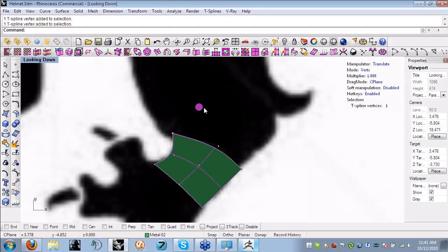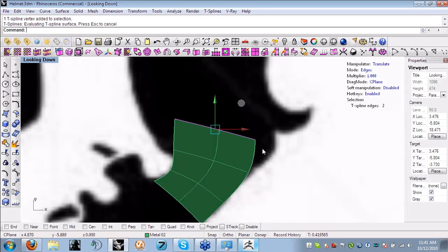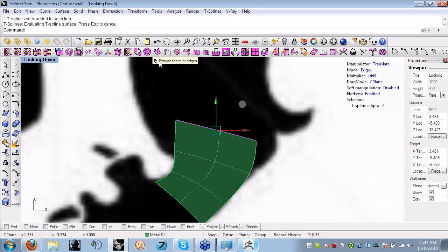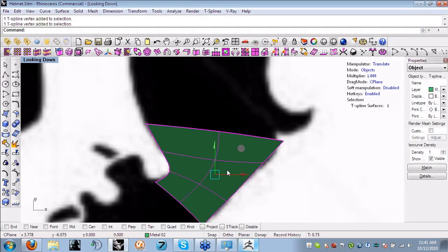So we'll go here. And I think hold Alt and drag, which is the same thing as clicking extrude. And again, I think the screen refresh isn't keeping up very well, but to get that into position, he used the rotate manipulator, and the way to get that rotate manipulator is to click on that blue text in the heads-up display until the rotate comes up. Then you can just drag the ring to rotate it.